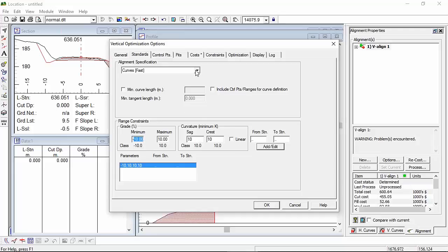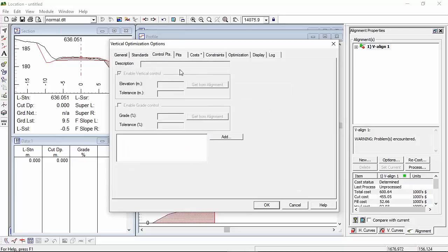You can, if you want, design roads with a simple polyline, straight segments between points. And in that case, you don't set the K factor, you set the grade break in %. But we're going to work with curves. So I'm going to set my K factor to the default here, which is 10, and control points.